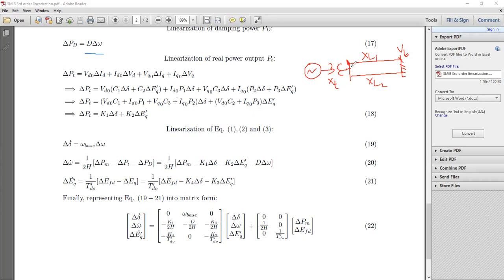An equilibrium point or operating point is one of the steady state points that your dynamic system may actually take. What is so special about the equilibrium point is this. Let me first tell this, and then I will go into how to find the equilibrium point for our system. For any linear system, there is one and only one equilibrium point. This is the beauty of a linear system.